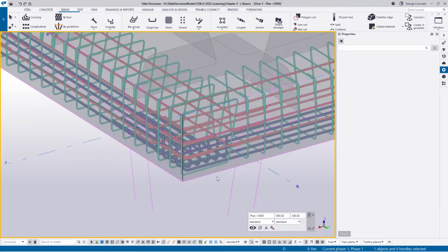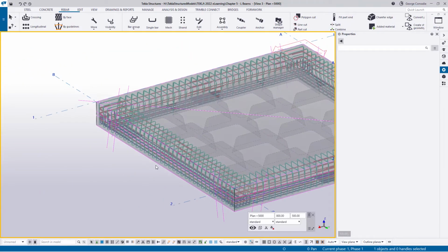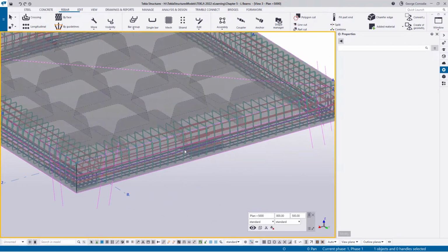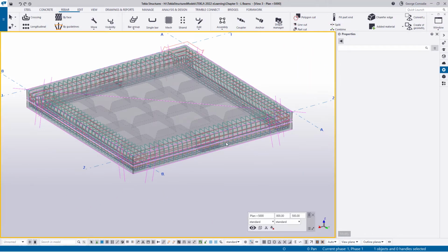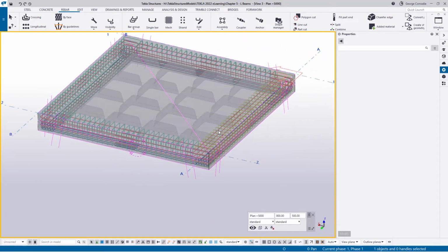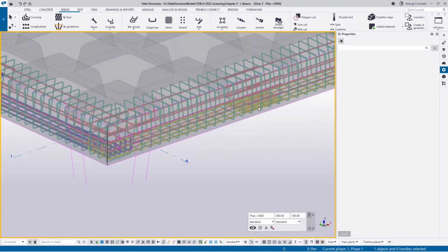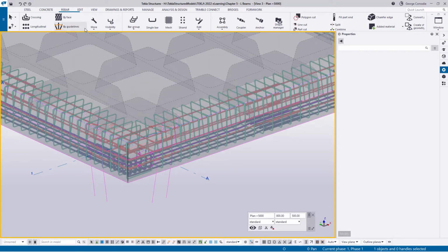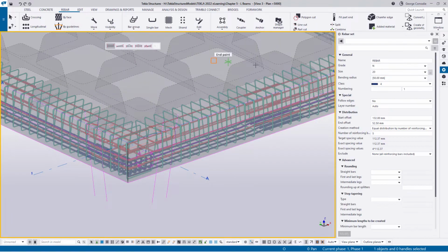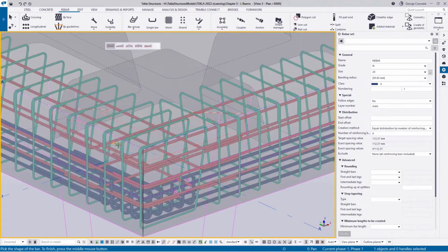So what I'm going to do, yeah, this is a bit of a different scenario. We'll use the same method as we did with these bars, so I'll just swing this around so I can actually see what I'm doing. I'll go to more, then point input, and it's still at 24, and I'll wipe out our offsets. This time we'll have a number of, and the number of will be 6. Let's just increase it, and then I'll draw the bar in again.